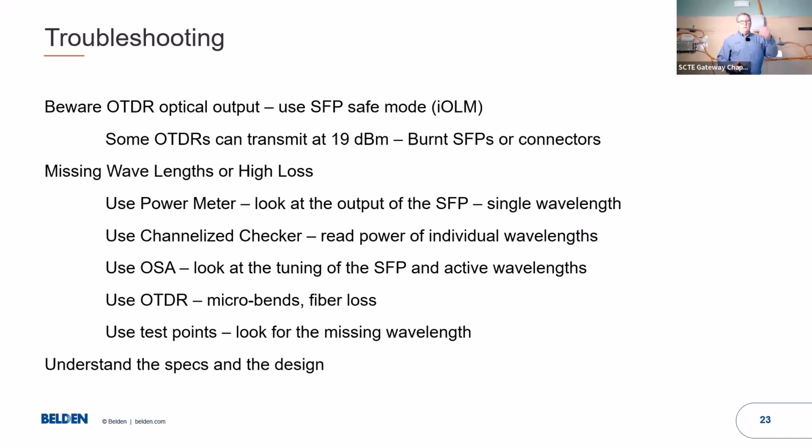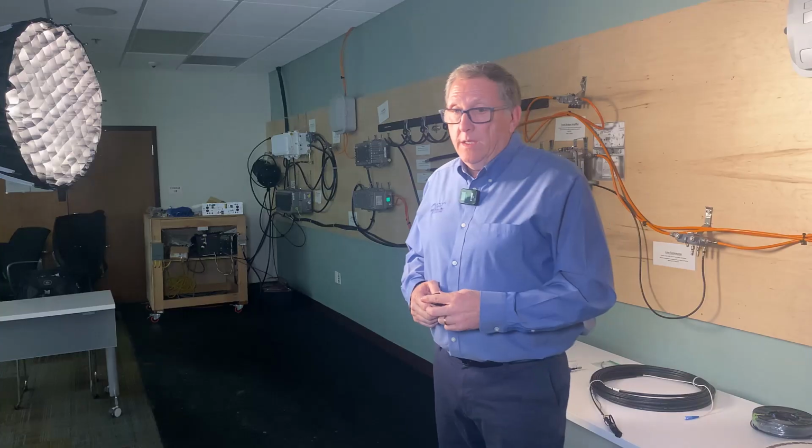There's been a lot of, as we swapped through, a lot of outages where the head end was saying, I got light leaving you, but nothing's coming back. And plant is saying, well, I got light leaving to you. And, you know, it's a burnt out optic. Pay attention to light levels. Pay attention to what the design is and what you're working on.